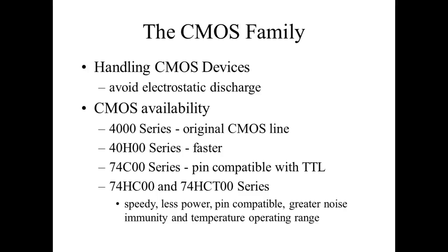So now what could you do? You could screw around and mix them up, and you saw a 7400, and you said, well, the only difference between these center letters is the speed and the power, and the pin out's the same. Well, the pin out is the same, but a 74C would not drive a 74 series TTL gate. So then they came out with the HC and the HCT. The HC will drive them, but not many, and then the HCT basically will drive TTL gates without any problem. And y'all dealt with an HC and HCT in one of your first labs. These are CMOS. The HCs and the HCTs are pin compatible with TTL. The HCTs will work in a TTL circuit.